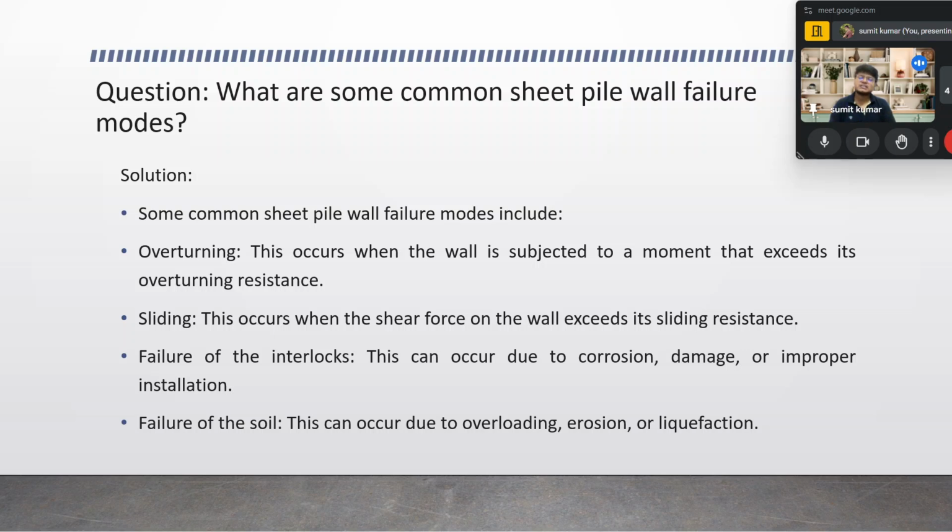The reason behind that is liquefaction. The problem associated with it is that the drawdown of the structure takes place into the ground because liquefaction takes place, and that's why the soil is liquefiable during the vibration of the earthquake motion. So in a similar case, if the soil is susceptible during the earthquake, liquefaction may occur, and in that case failure takes place, and the sheet pile goes down into the ground.